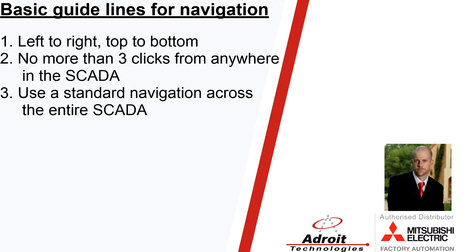Second one that I like to keep in mind as well is no more than 3 clicks from anywhere within the solution. Now, I know that doesn't sound like a lot, but it's a good rule to try and stick to. You don't want your operators clicking their way just to turn something on or turn something off or check a value. And I'll show you some examples a little bit later on of what I'm talking about here. But typically, you should be no more than 3 clicks within your SCADA.